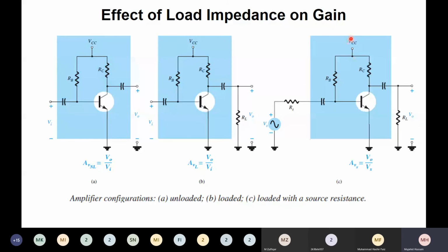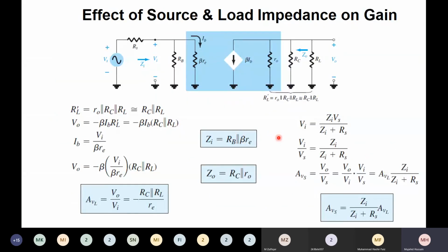This is the source signal which is applying the signal to the amplifier, so it will stay as it is. By simplifying and rearranging the source and replacing the transistor with its re equivalent model, this is the final circuit after applying the AC analysis on the transistor.